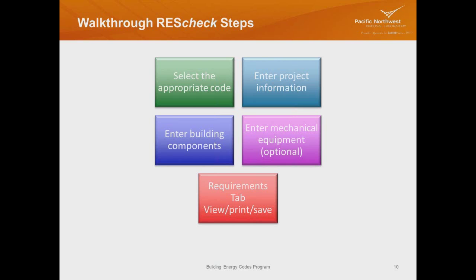The first thing that you'll want to know is what code. REScheck has options for several codes, and the Department of Energy supports the most recent published IECC and then two versions back. So you could be in the 2012 IECC, or your state or location might have just adopted the 2015 IECC. So it's really important that you know what code is applicable in your location. If you don't know, you can go out to our state pages, and the REScheck software has a link that'll take you out. I think I have a screenshot of it in a little bit that shows you the status of state codes.